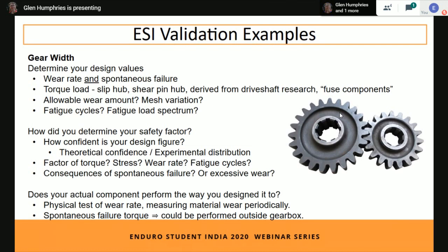Anyway, before we get to that, of course, we need to know how much torque they're carrying in the first place. How do you calculate these things? So, torque load. In the past, when we've been talking about torque, we talked about maybe having a shear pin, and in theory that sort of works for these gears. You could make gears with an extended hub where all the torque is carried by a shear pin, and when the shear pin fails, you know that a certain measured amount of torque has been exceeded, but that becomes very difficult inside a gearbox.